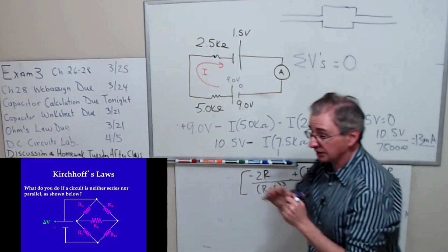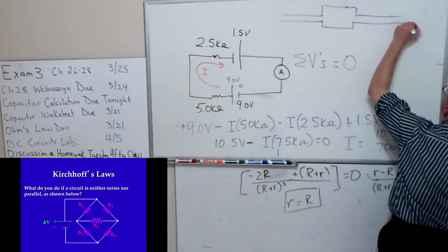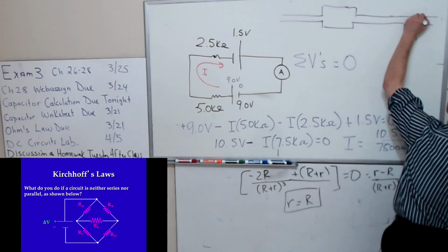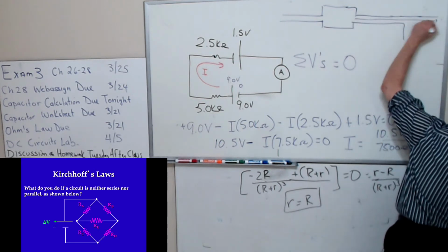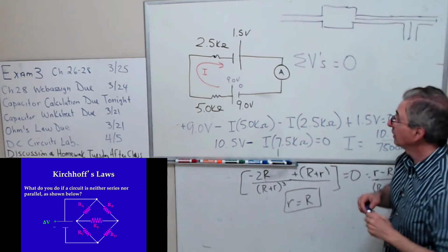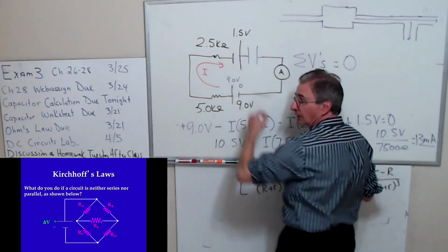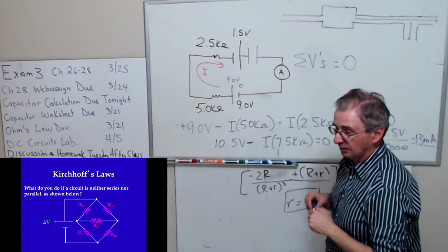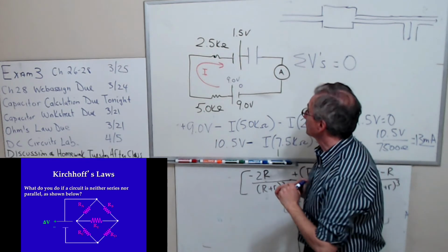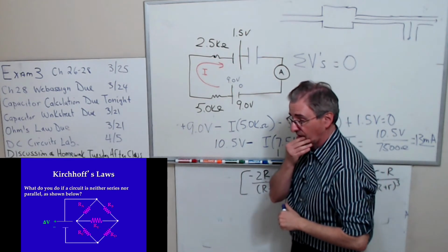Yeah. Thanks. The only way the current's going to change is if you have a T. Okay, it's not a good T, but water can go either this way or this way. Just think of it in terms of water. So that's the only way. There isn't a second path, right? If I put a capacitor here, I have not given the electrons a different path. So they still have the same path, and the current's still going to be the same. It's a good question to ask.